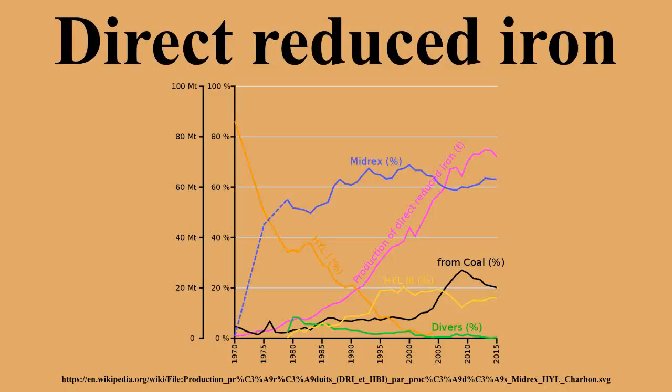The direct reduction process uses pelletized iron or a natural lump ore. One exception is the fluidized bed process, which requires sized iron ore particles. Few ores are suitable for direct reduction. The direct reduction process can use natural gas contaminated with inert gases, avoiding the need to remove these gases for other use. However, any inert gas contamination of the reducing gas lowers the effect of that gas stream and the thermal efficiency of the process.